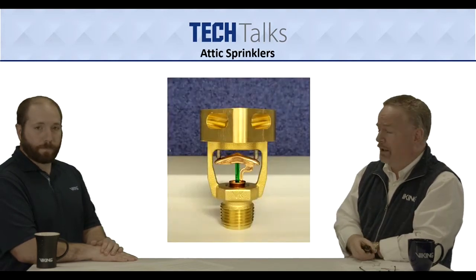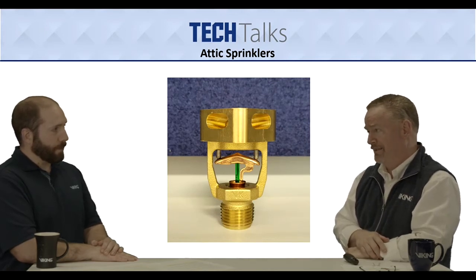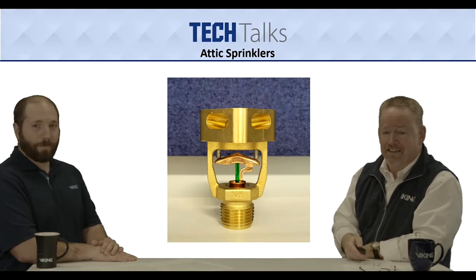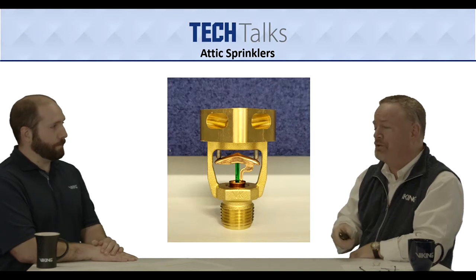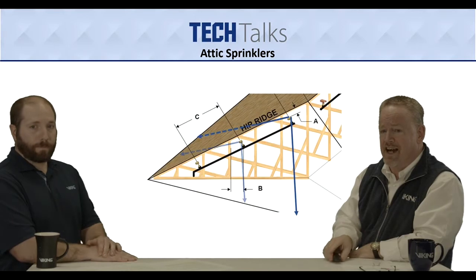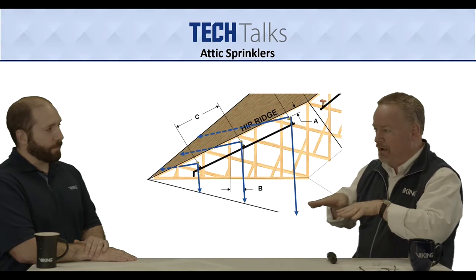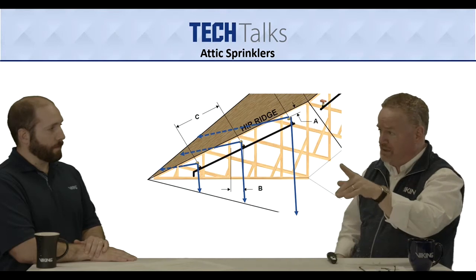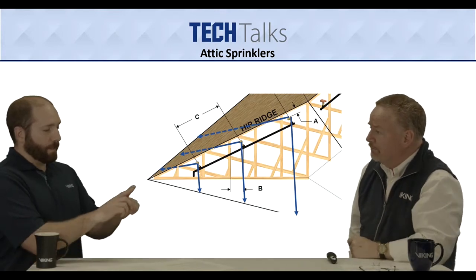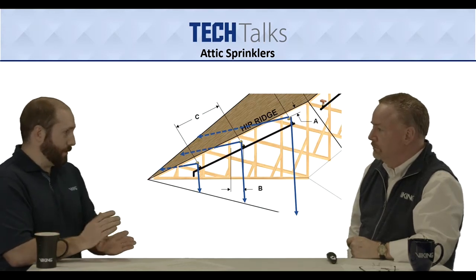All right, now let's take a look at the hip sprinkler, because the hip sprinkler and hip bridges have a really unique spray pattern. Absolutely. This one is designed to spray at about a 90-degree angle, so sprays come out of it at 90 degrees to go down each of the slopes from this hip ridge right here. So it's not coming out straight, but on two angles. And then they're going to be nested together at 6-foot spacing.